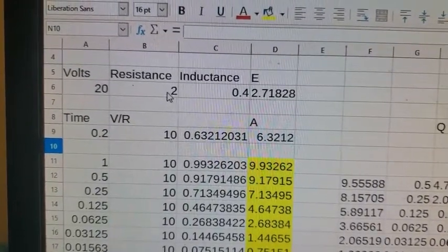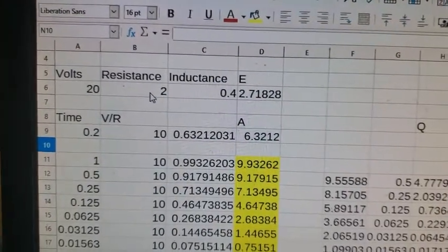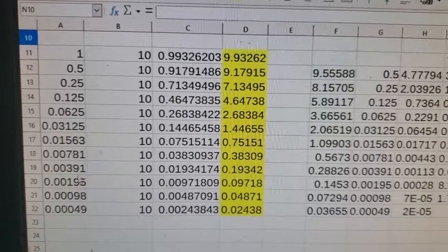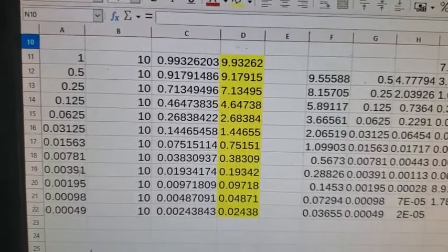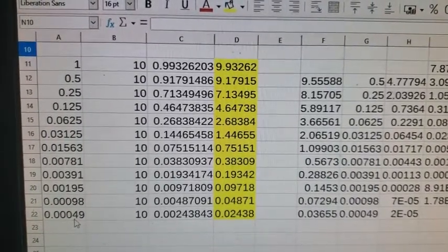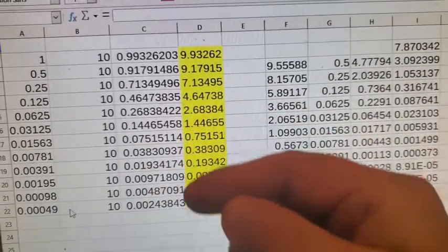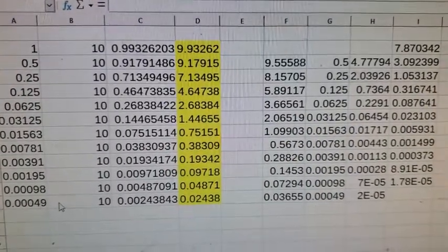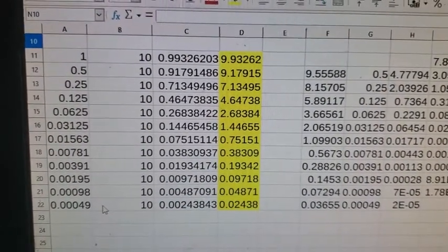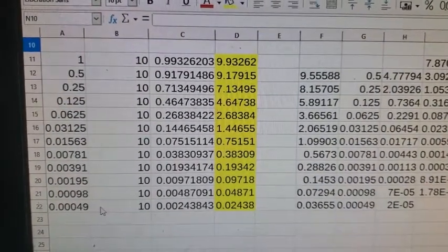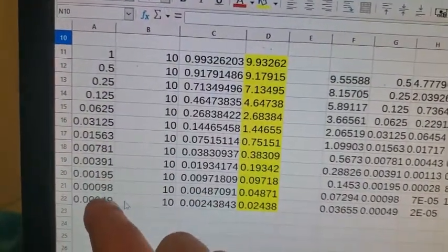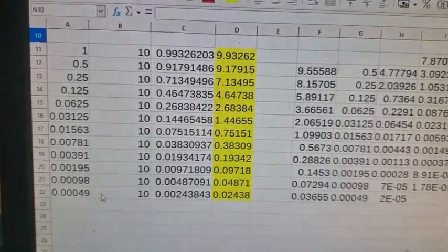Now, one issue there is if you want a low resistance coil, you're going to have big fat wire, and then you run into skin effect as you go faster. So that's another issue in the real world: as you go faster, you're going to run into skin effect, and the skin effect will decrease the effective diameter of the wire and thus increase resistance. And so that's yet another parameter to get into. One of the ways to get around that is Litz wire. And not to mention him every video, but you notice John Bedini always used Litz wire. Not always, but in many of his machines, you would see him using Litz wire. And so that allows you to go quicker without running into increasing resistance, not from Lenz's law, but from skin effect.